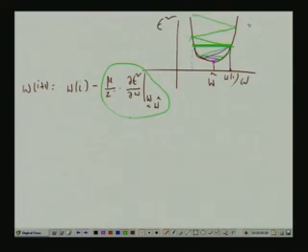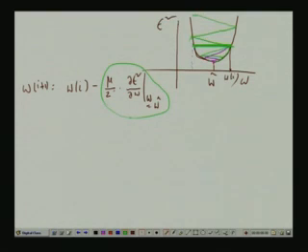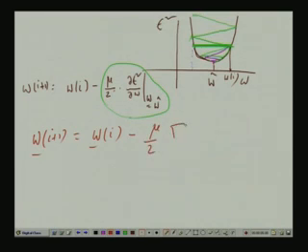Those upper bound expressions in this case are worked out, but I will not go into that, because I am not so bothered about the steepest descent algorithm. I want to derive an adaptive filter algorithm from this. So, in the more general case, what does this mean? When you have not a single tap but multiple taps, from W i vector you go to the W i plus 1 vector, where i is the iteration index, by subtracting from W a quantity proportional to the gradient vector.